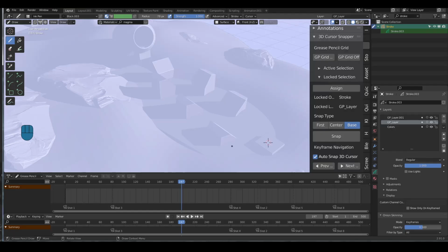Through some further experimentation, I found an even more fun way of pathing out a path. Okay, so I've got my grease pencil down here. If I put the cursor on, you can see that there's the canvas. But I'm going to try something different now. I'm going to switch it to surface mode, and when you do, make sure you drop this down a bit, so like next to nothing, because otherwise it'll be slightly above the ground.